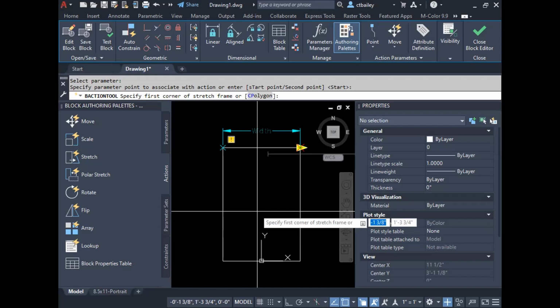This is new. We know how to do selections by a crossing, right? Or we know how to do selections by a window. Window gets me what? When I select something with a window, what do I get when I use the window? Thinking the window we just made? No. What window are we talking about? Your selection window, depending on which corner you put. Is it blue or gray? Okay, we'll let you think. Blue gets you everything. Green gets you everything it touches. Crosses, right? So it's the same idea.